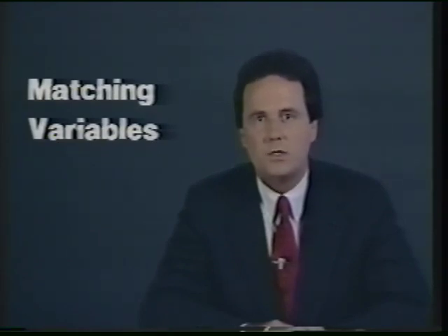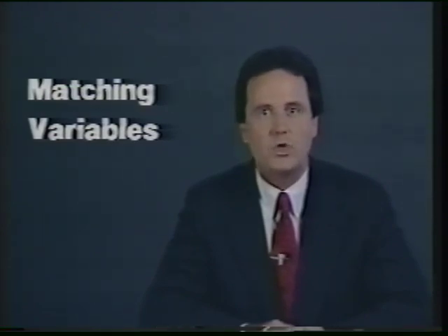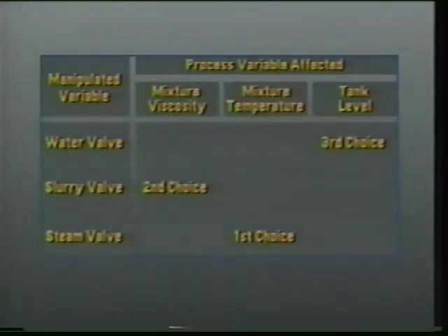In making this match, we would ideally like to have the process variable respond quickly to whatever change is made in the manipulated variable. In other words, there should be a minimal lag between the manipulated variable and the process being controlled. It is also desirable that the selected process variable be easy to implement. That is, quick delivery may not really be the most important factor. In order to pick the best solution, examine your list of manipulated variables and process variables, and then first make the most obvious choices for solving the control problem.